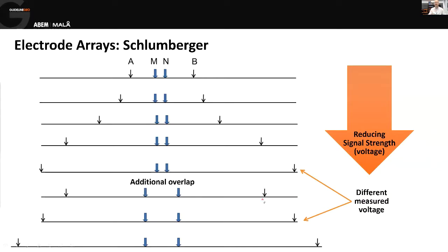So we actually take a step back with our current injectors, take this measurement again, but with the new voltage pair. And that allows us to then be able to adjust to account for the fact that the signal steps up at the point where we change the spacing at the center.